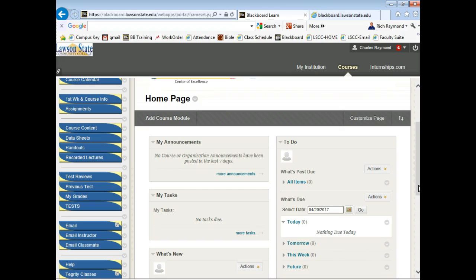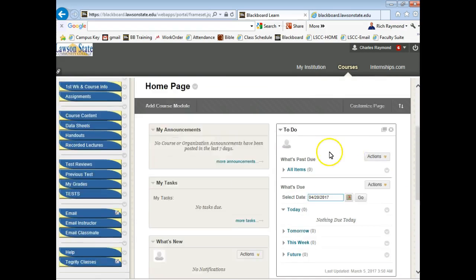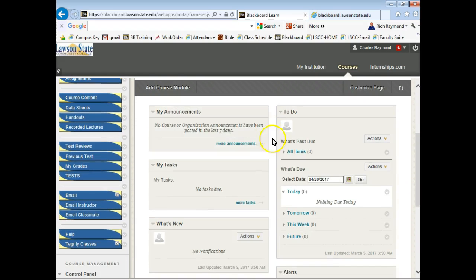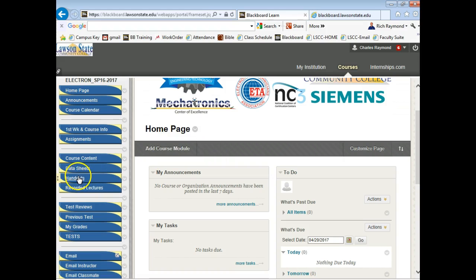So this uses an enable. It's not even edge triggered. The 7476 is edge triggered. So this little circuit that I've got right here would also be included inside that integrated circuit, right? But if I wanted a JK flip-flop, I wouldn't build the JK flip-flop. I'd buy it, right?